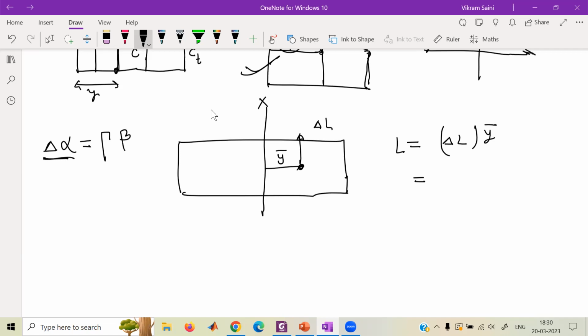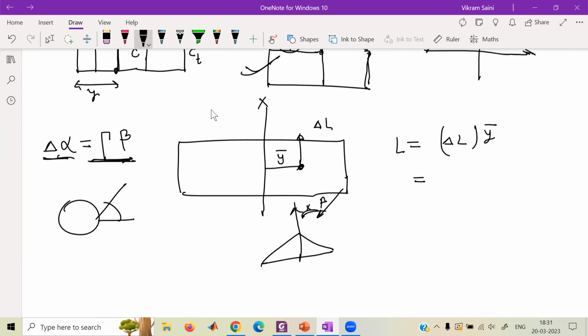Okay, gamma is the dihedral angle and beta is the side slip angle. Okay, side slip angle means you're looking at the aircraft and this is the x-axis of the aircraft, but the relative wind is coming from this direction. So this is angle beta. So delta alpha on the leading wing is this magnitude. So corresponding to this delta alpha, you will have a delta lift that will be CL of the wing multiplied by delta alpha, right? CL alpha. What else?